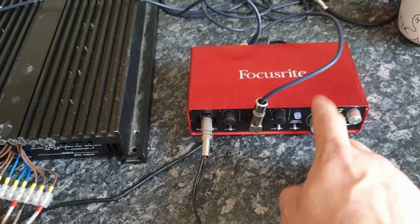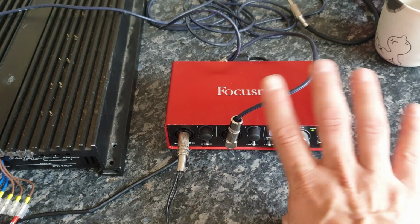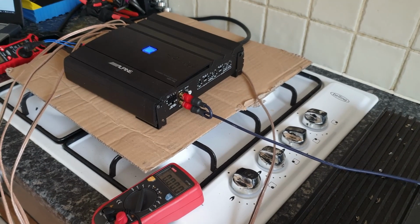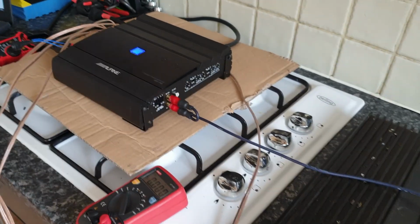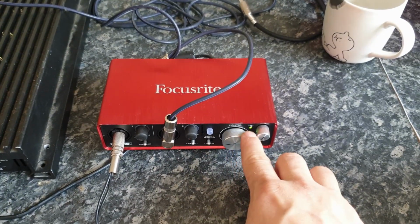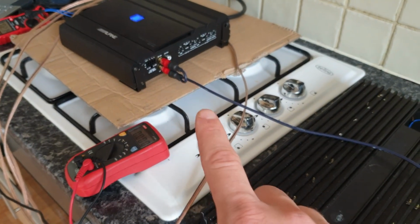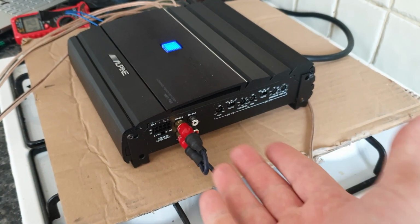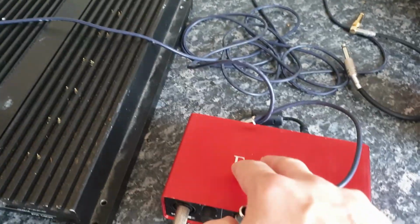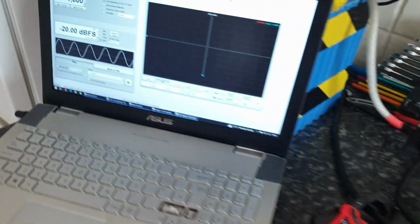I know that this audio interface gives me about 1 volt full scale output, and this amp needs 4 volts. So all my amplifiers are going to be tested at less than 1 volt, probably even like 0.6 volts, and I'm going to tell you why. First, I'm going to maximize the output that goes into the amplifier. The gain on the amplifier is turned all the way to the minimum. Now I need to gain match, basically, to match 0.6 or 1 volt to make sure that it outputs as much as it can.